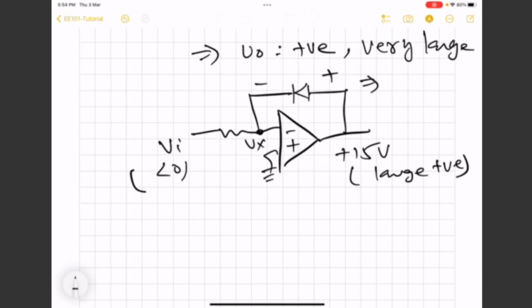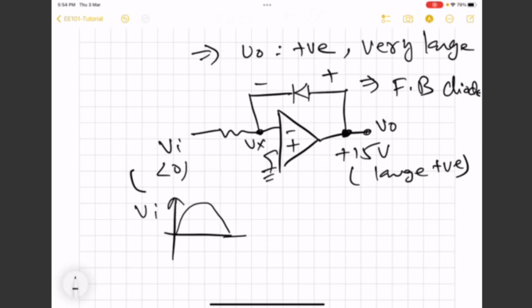So this implies forward bias diode. So diode will get a forward bias. If it is not forward bias, this voltage will keep on increasing till it achieves the 15 volts, because here you can see that Vi is increasing. So it will definitely switch on. There will definitely come a moment when this Vd is greater than 0.7.